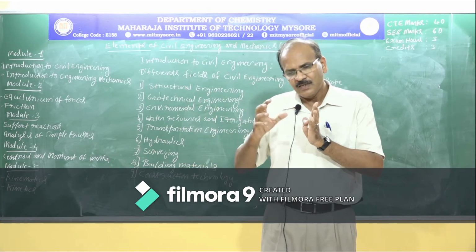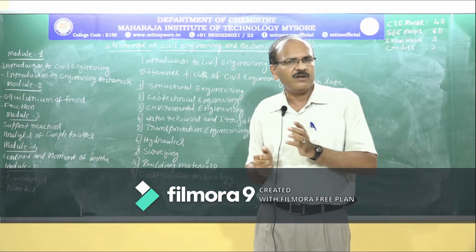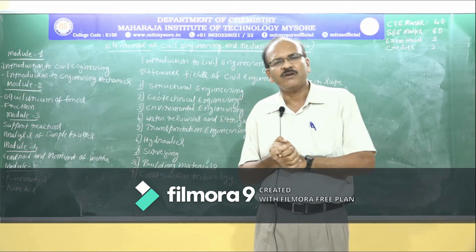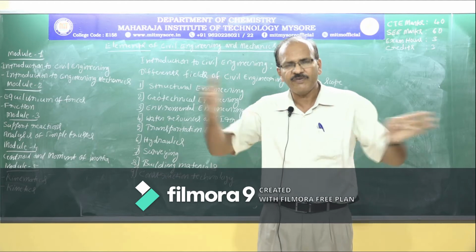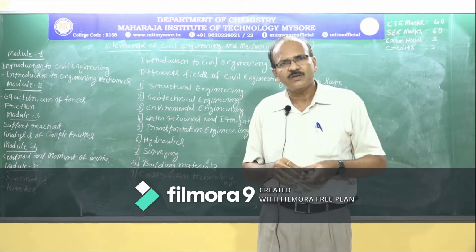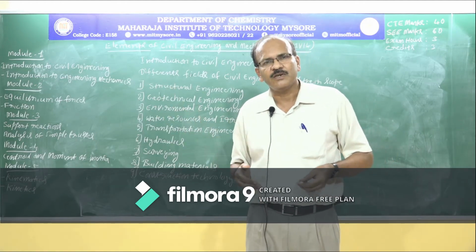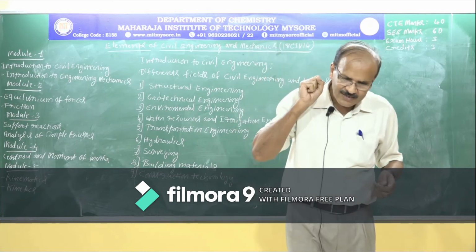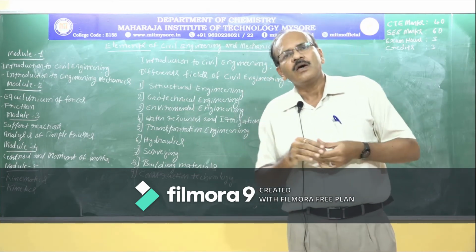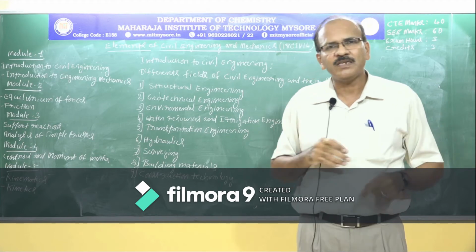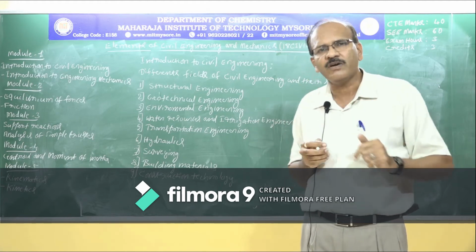So between that you will have a certain quantity of soil per unit weight of soil. Similarly for different sizes. So that is called grain size distribution. So those grain size distributions affect the safe bearing capacity of the soil and also the settlement of the soil.